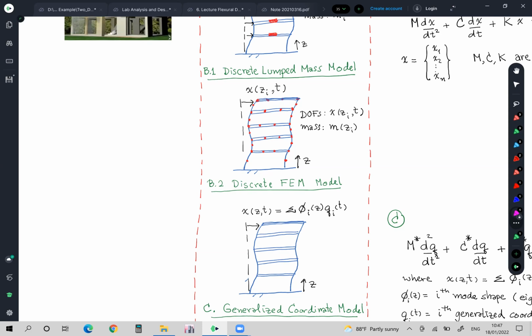And generally in the 3-dimensional model, for each node, the degrees of freedom number 6. We are talking about the movement of each node, which is normally described by the movement along X, along Y, along Z, and the rotations about the X, about the Y axis, and about the vertical Z axis. So in total, normally it's 6 degrees of freedom, right?